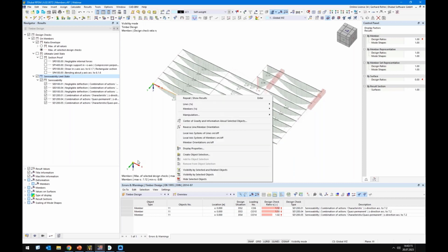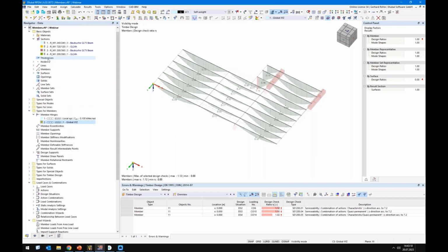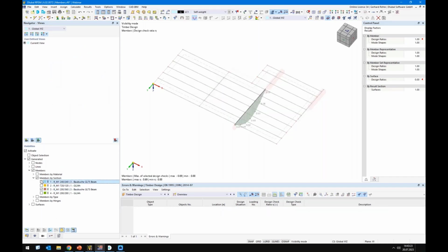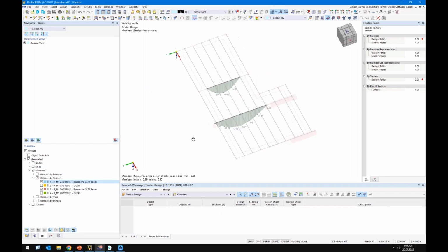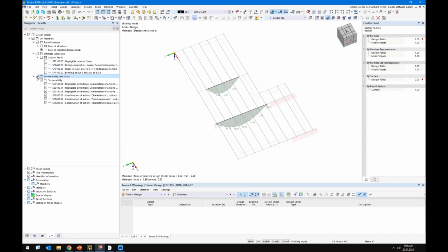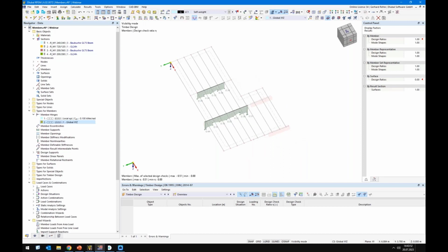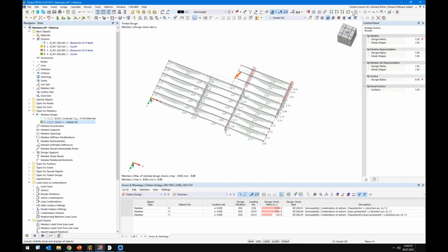Okay, and let's check also our Baubuche beams. It was section number 1 and 3. So we have a ratio for SLS of 69 and 62, and ULS extremely small. So maybe worth talking about changing it to 320 millimeters. So now we have 200 by 360. Then we can change it to 320, but that's okay for now. Okay, so we remember the ratio.